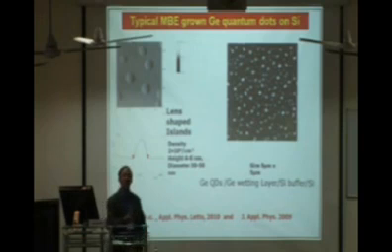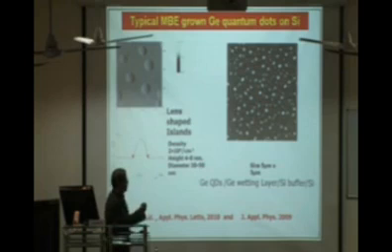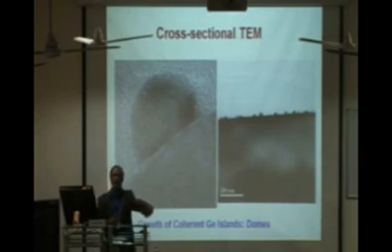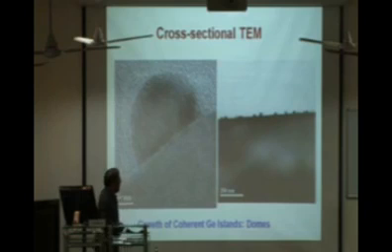That's why I said it's very difficult to get monodispersed arrays of quantum dots in self-assembly. Actually, they will be of different sizes. But if you can be choosy, you can choose some of them and try to make devices. If you have a very good lithography system, you can make single quantum dot devices.